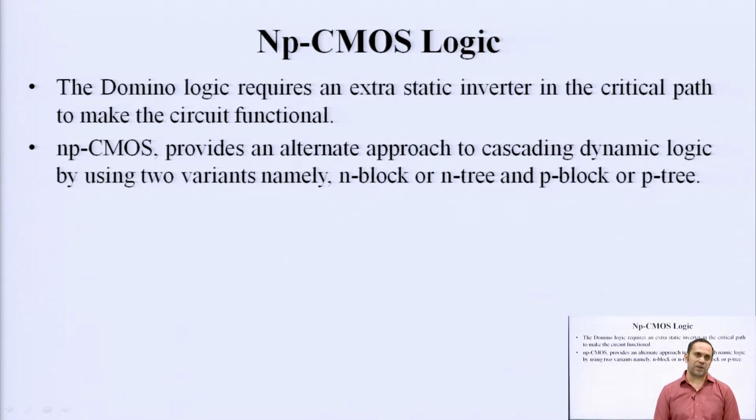So, some amount of energy is always lost in turning it on. To pass a logic 1 through an NMOS transistor will require a finite amount of positive voltage, the so called threshold voltage. P channel devices on the other hand, work on negative threshold voltages. So, they can be considered as easy to pass a logic 0.